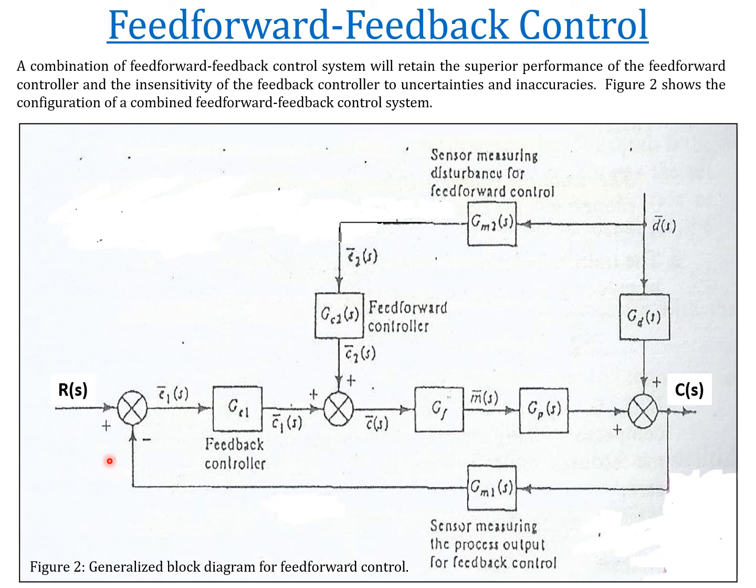But if we just say conventional process control, it means the normal feedback control with PID methodology. The feedback will be tuned normally. The feedforward will be tuned either on the computer or by the standard method you used just now, just the gain.